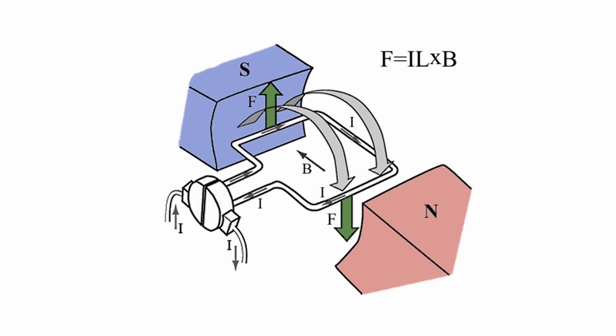Most electric machines contain the same basic components for exploiting Faraday's law. There's a rotor, a central armature which carries current and rotates. There's a stator, a stationary component that sets up the B field. Then a commutator, or a control device, which ensures that the current flows with the right direction and timing through the coils. And low friction bearings, which allow the rotor to spin and produce torque. This arrangement can be varied in a few ways for different applications, but the underlying principles of operation are very similar.